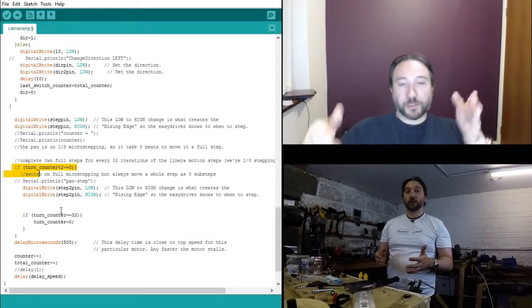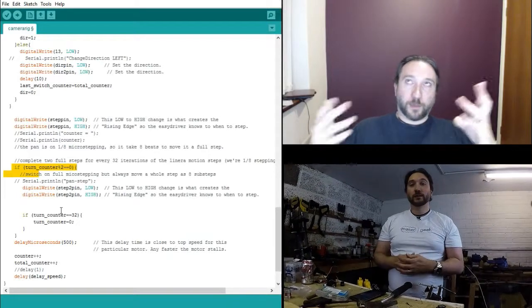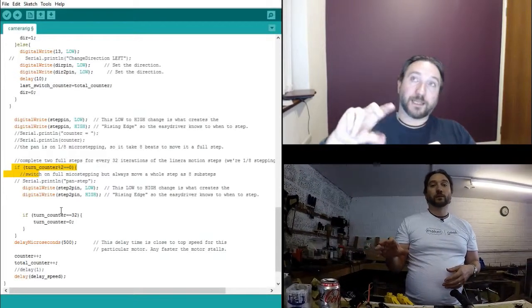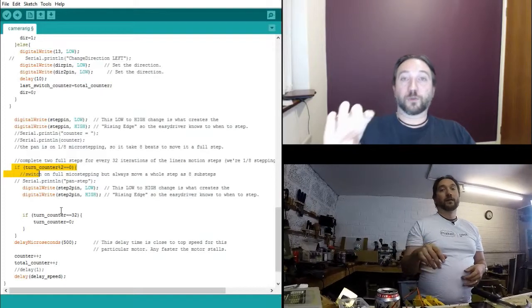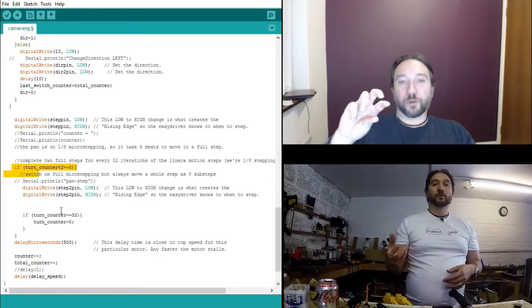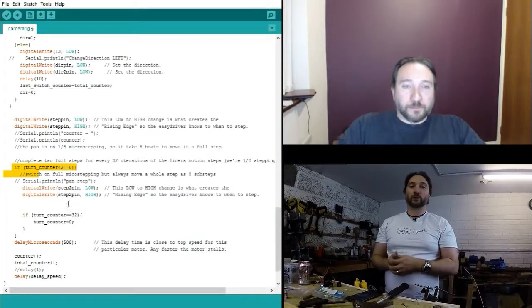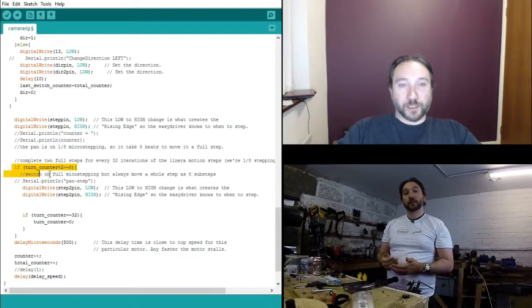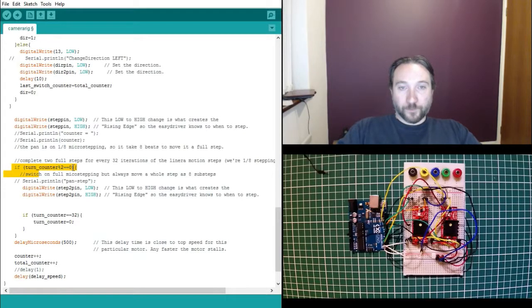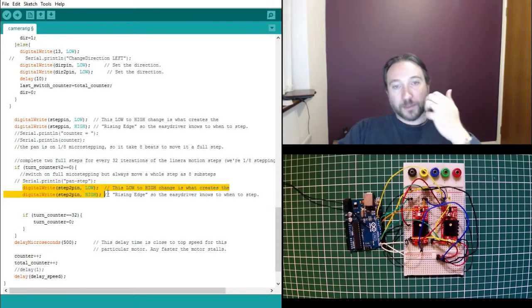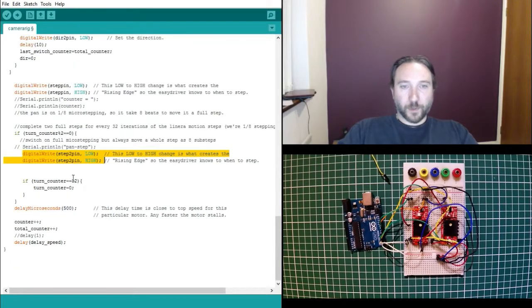So the reason I chose 32 is because the stepper motor is doing 1/8 microstepping, so it actually takes 8 step signals for it to do a single rotation, and I wanted to do 2 of those in a batch. I probably didn't need to do it this way, but that's what I did. So essentially, for every step number that's cleanly divisible by 2, I do the same low-high step signal to the pan motor. Then when I get to 32, I go to 0 again.